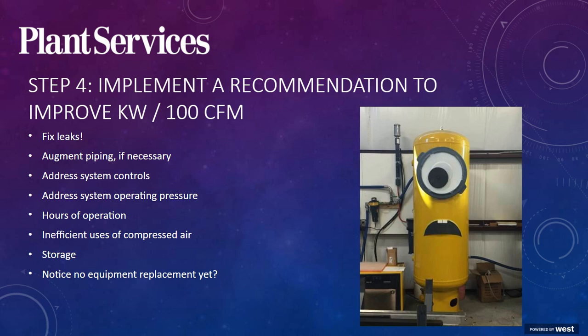What else can you spy to change in your compressed air system? And we mentioned in the case study that there were two 240-gallon storage receivers. Those were decent sizes for the modulation control, and now knowing the actual operation, storage volume there was sufficient. However, if you had different controls, load/unload, VFD, or you were adding compressors, that storage volume may be severely deficient in adding that necessary control buffer for your compressors to cycle. The great part about storage is that, save for the demand drain, there's nothing mechanical.